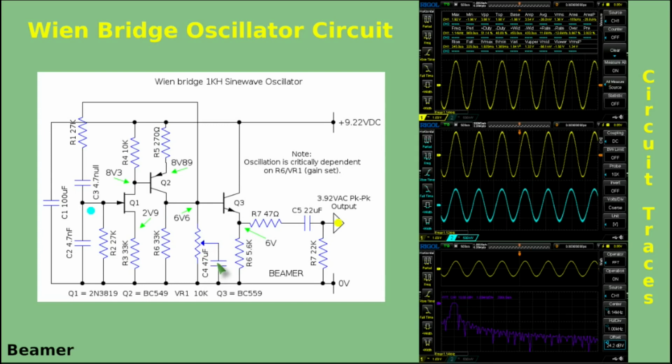The other point I would like to make is that the Wien Bridge oscillator really requires two features of the circuit, and that is that there is a low impedance driving it and a high impedance seeing it. Well, I've accomplished the high impedance. This is similar to the phase shift oscillator. I've achieved that by using a JFET. It's a very high impedance here and doesn't load down the filtering networks of the Wien Bridge.